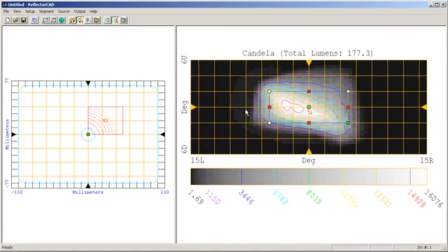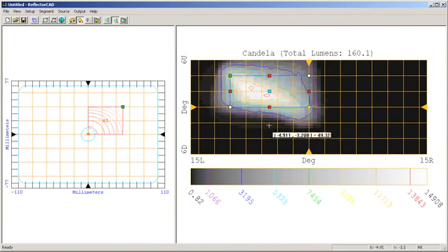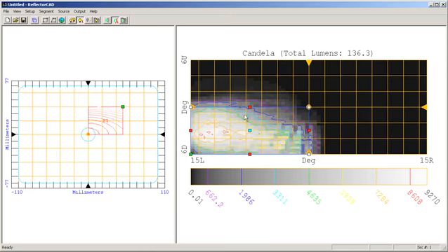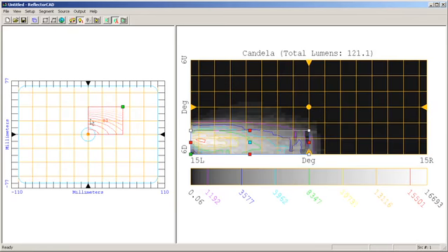As I mentioned previously, ReflectorCAD is an entirely new paradigm. In fact, what I will do is operate on the luminous intensity pattern, changing that pattern to the desired shape that I want from that particular segment by dragging and dropping the various areas around the luminous intensity pattern, and ReflectorCAD will automatically update the shape of the segment in order to produce that particular luminous intensity pattern. Now, in the segmented area of the display screen, you will see a series of contour lines in the particular segment. What this indicates is whether this new segment is above or below the base surface that you've identified.